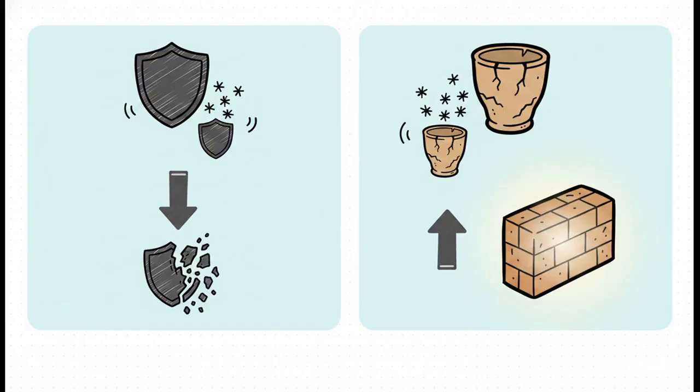It ruins the toughness. However, take a naturally brittle plastic like polystyrene, add that exact same 30% glass fiber, and its impact strength more than doubles. The complex chemical and physical interaction between the base polymer matrix and the filler fundamentally flips the impact behavior. You just can't guess. You have to test it.